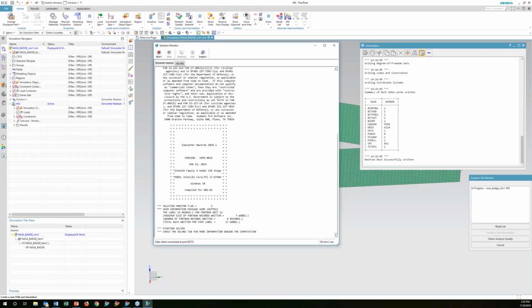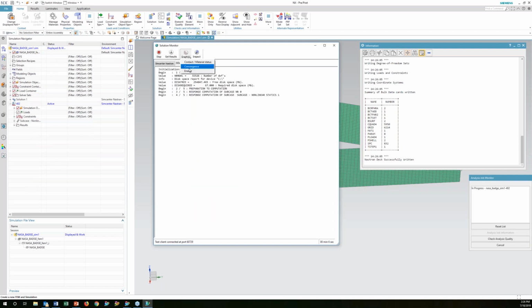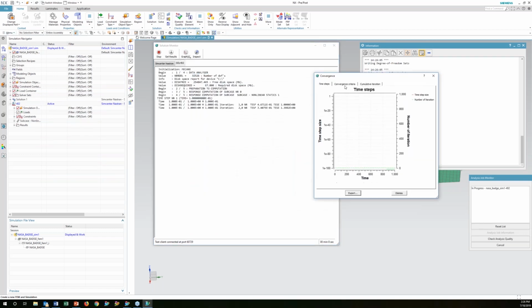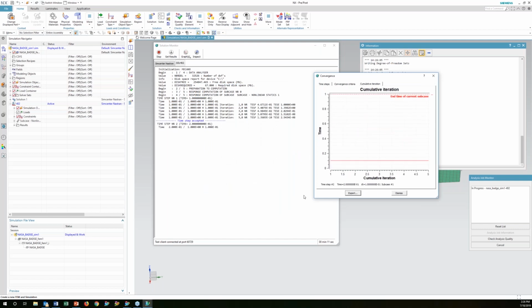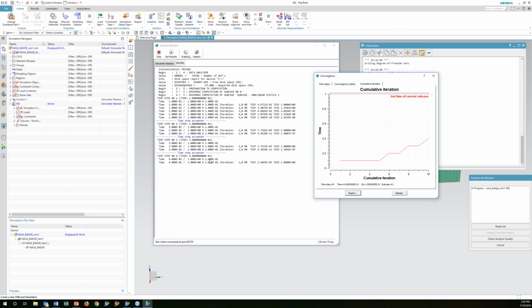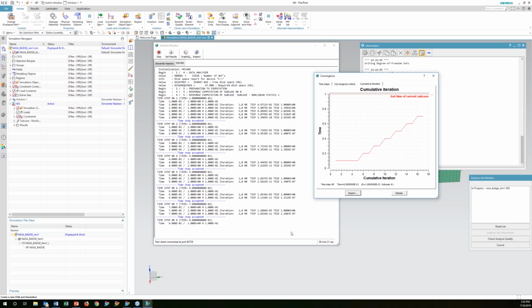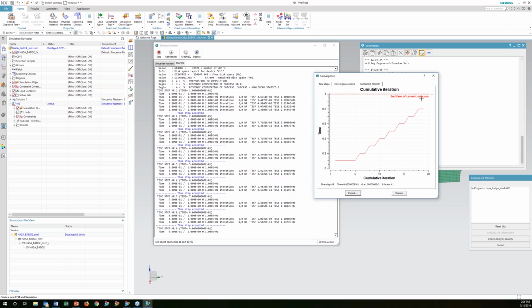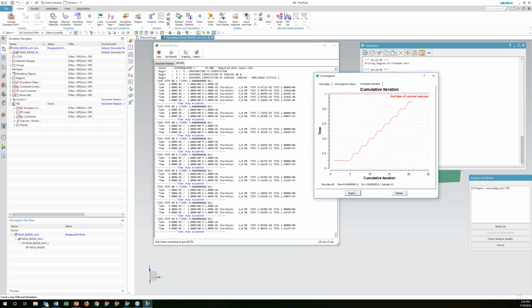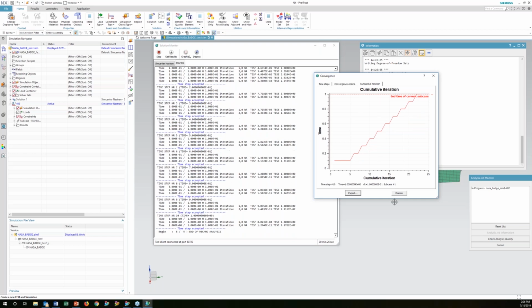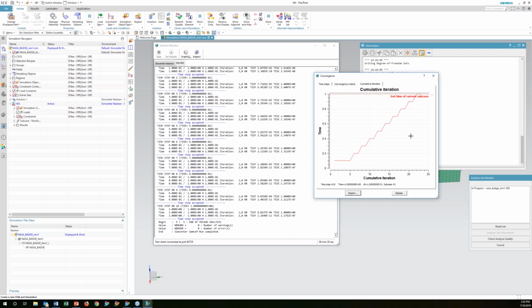Now, this one, we can go ahead and select this 402 tab. You'll see it run through. We can go ahead and plot a simple convergence graph of the iterations. And you notice it's going through my time steps, and I broke it down into 10 time steps. You'll see it go through the solution at 0.1, 0.2, all the way up to 1. And this, I don't have anything crazy nonlinear. I didn't even toggle the nonlinear, so it's working nice and smooth.